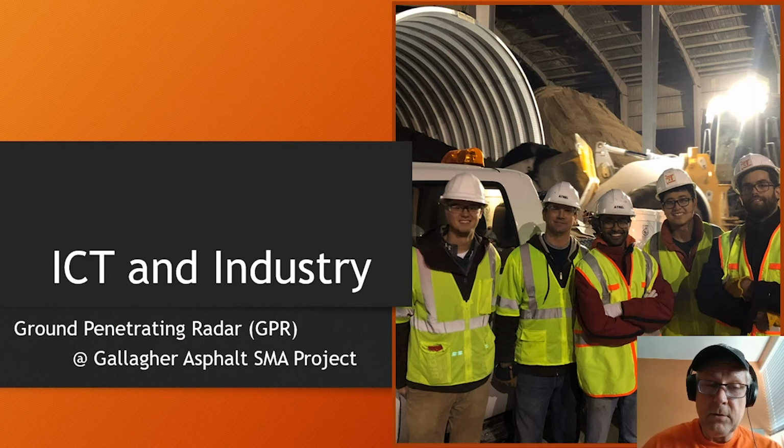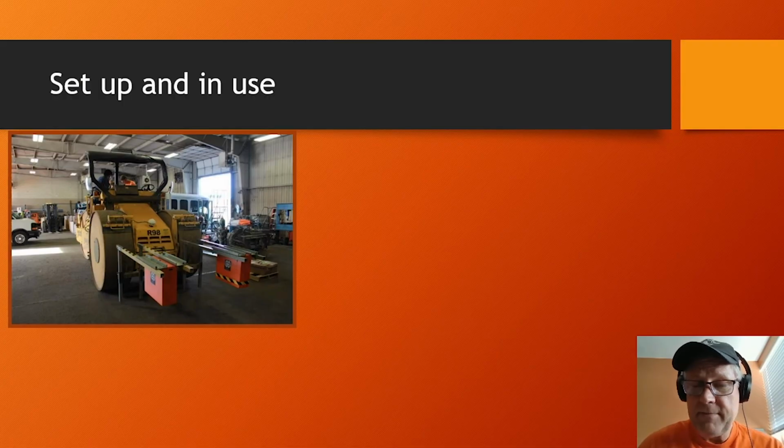The Illinois Center for Transportation and Industry is an example of working on research, and they do publish their findings. They're looking at ground penetrating radar to help see if it'll measure density on the asphalt pavements quicker, efficiently, and across the mat. If it does, we have more real-time data, and we don't have to wait for cores to know how good or how poor we're doing while installing the asphalt.